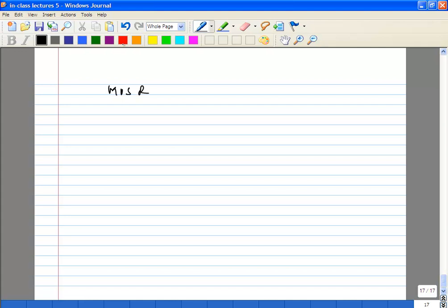Obviously, we looked at this during the VCO. MOS resistor, if you want really mega ohms kind of resistance, you can use this. You can use a MOS resistor with a very small W over L. Okay.